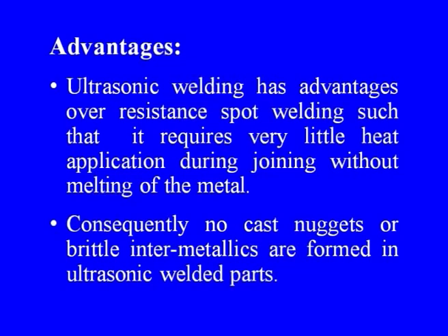The advantages of this process are: ultrasonic welding has advantages over resistance spot welding, such that it requires very little heat application during joining without melting of the metal. Consequently, no cast nuggets or brittle intermetallics are formed in ultrasonic welded parts.